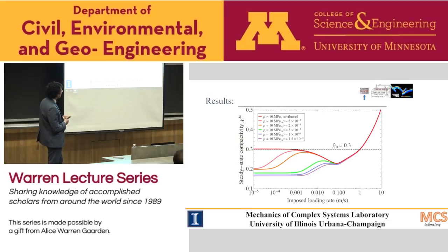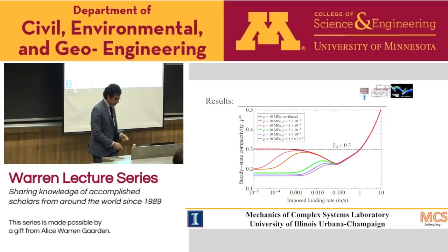So at a higher vibration intensity, although you start with a very compacted specimen, eventually what you experience is almost monotonic dilation. So in that case, you wouldn't expect stick-slip, whereas in these cases, you would expect stick-slip. Because these are non-monotonic, while this is monotonic with dilation, then it will just be steady sliding. So what are the implications of this?